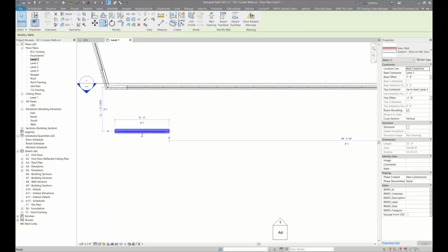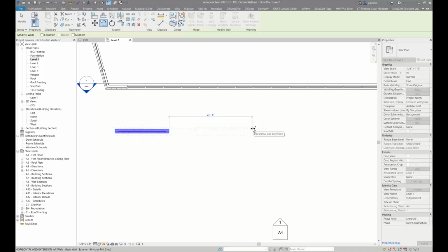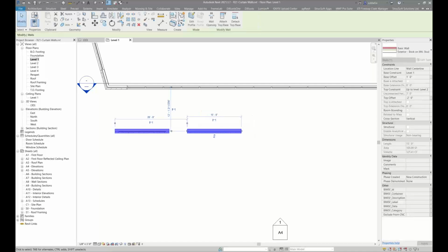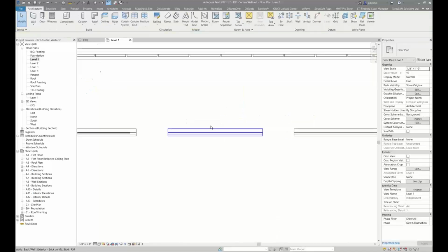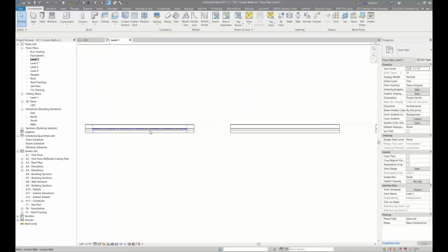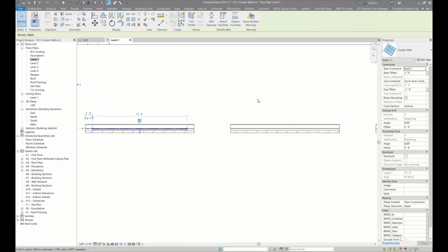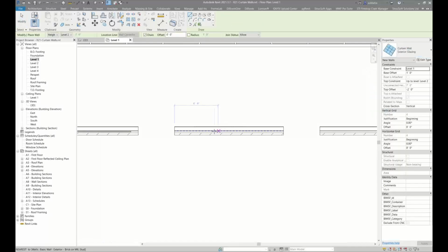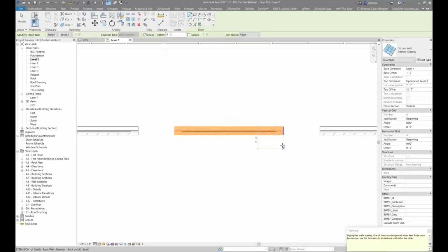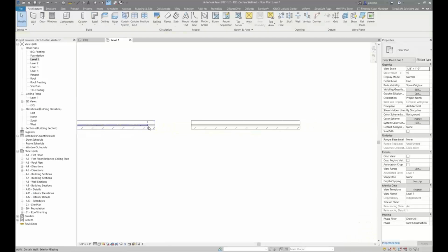So I'm going to just copy this wall over again by, let's say 20 this time. And then again, copy this wall over by 20. So now we have just the brick walls, and then the first one we created was the curtain wall. All right. Okay, I'm gonna go ahead and create similar, and we're going to create the exterior glazing, and I'll follow the same rules, 1 foot away, and I'll make it 13 feet. Enter, and you'll see that again, it didn't cut a opening in the wall.